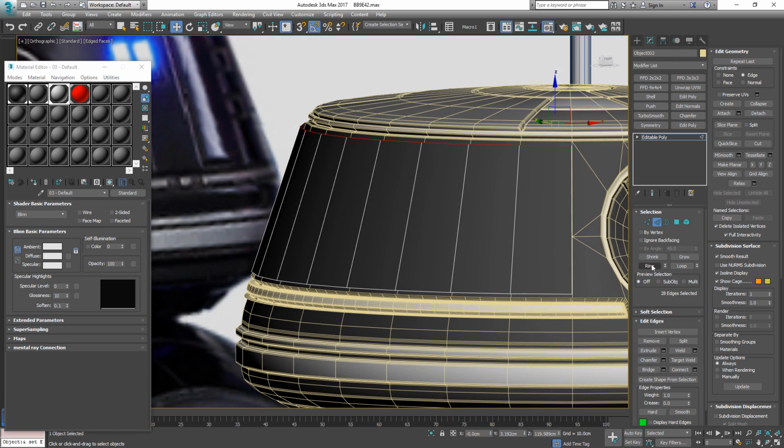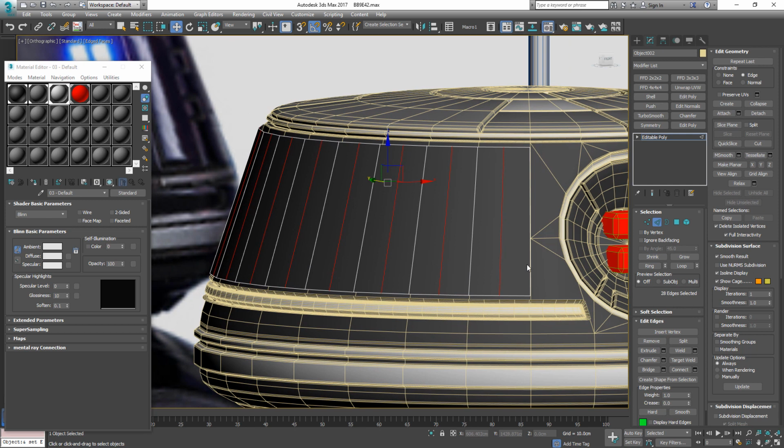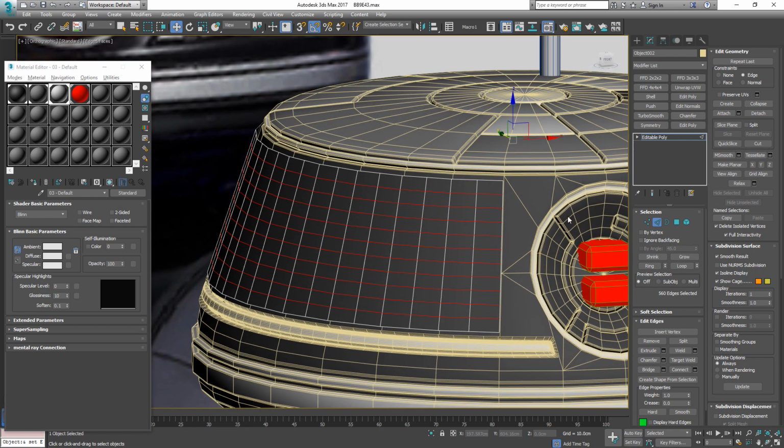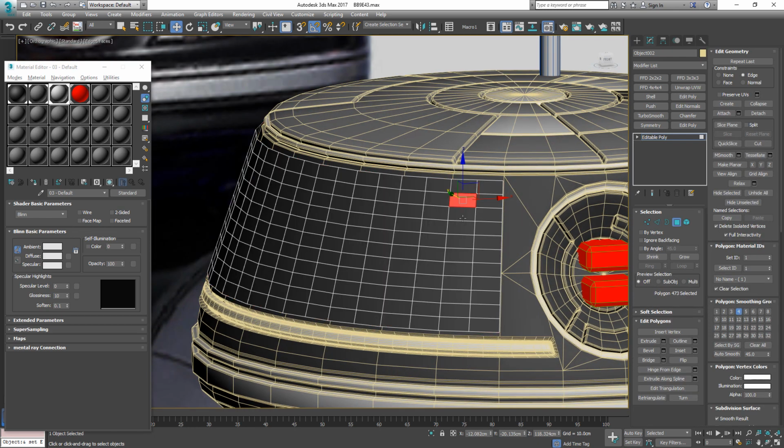So let us make a ring connection here so that we have both edge loops at the top and bottom, and then connect it with one intersection each there in the center. Now let's just select all of them also as ring, and we're gonna add 10 horizontal edges here, so that we have some polygons here to work with.